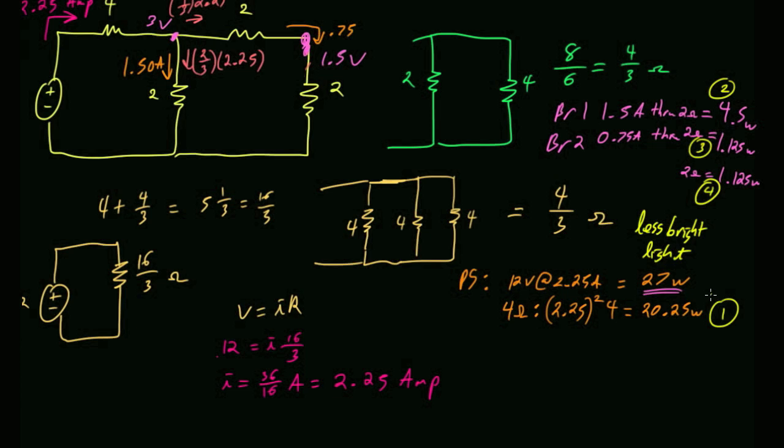So we started by generating, over here we had 2 amps, on that side we had 2 1/4 amps. Let's see, in branch 1 we had 1 amp. Now in branch 1 we have 1.5 amps. Okay, so that was actually the rationale that made the most sense. We drew more current from the supply, but by decreasing the value of this resistor, a lot more current went through it.